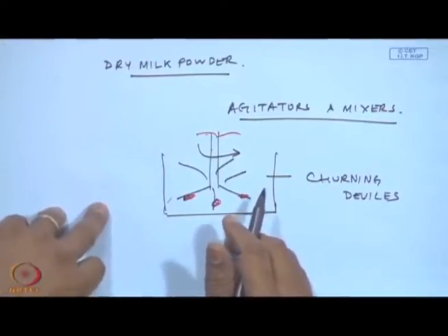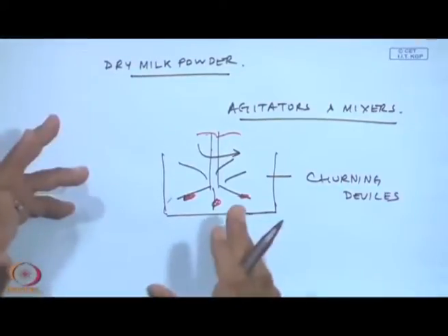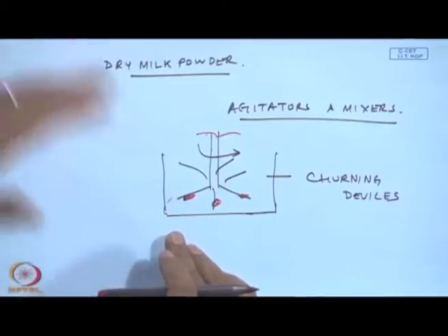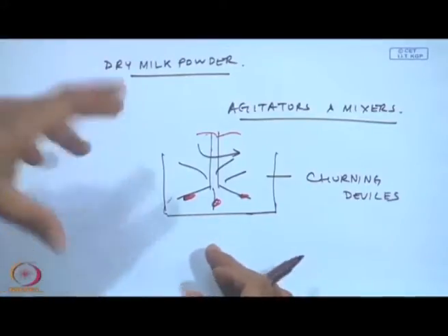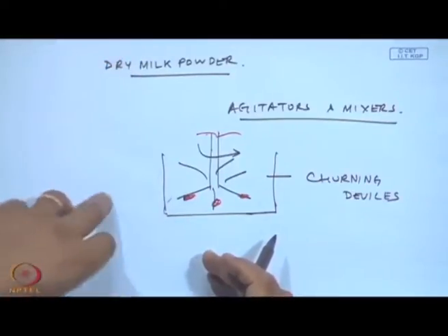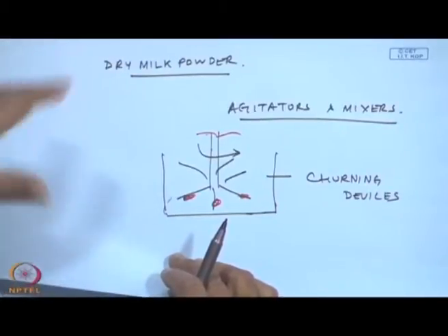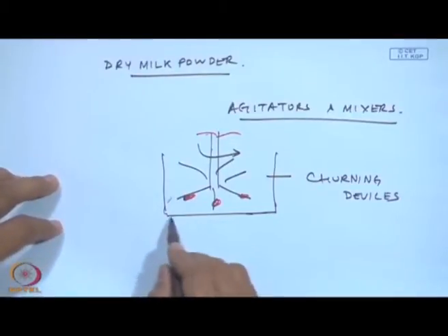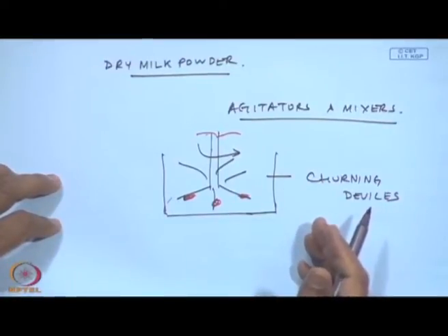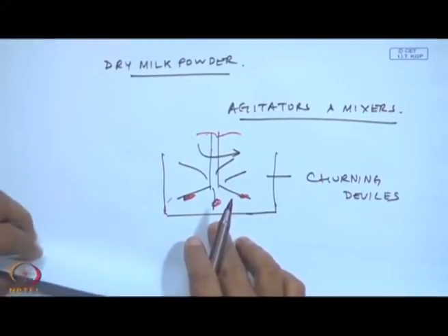Again these things happen. So, periodically in many of these plants, be it the FD fan in a power plant, or an agitator in a food processing plant, in regular maintenance they scrape off the deposits, and there are alarm levels also. If suddenly they see that the weight increases, they know that something is getting deposited. You are talking about an iron ore sintering plant, a lot of things happen. A lot of places where things can get stuck, they will create an unbalance and then things will break off. So, the sources of unbalance are manufacturing defects, installation issues, maintenance issues, and so on.